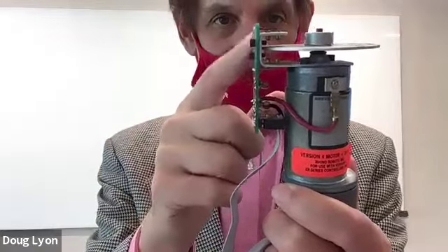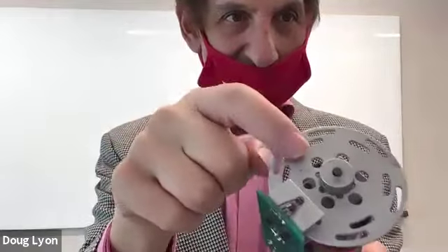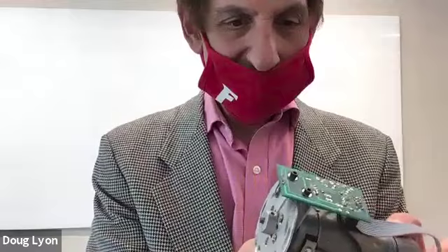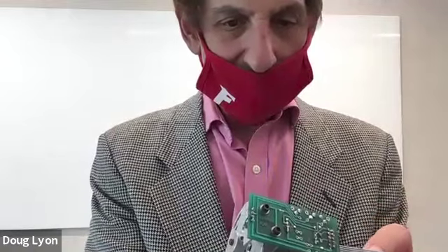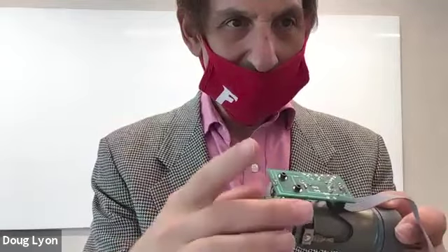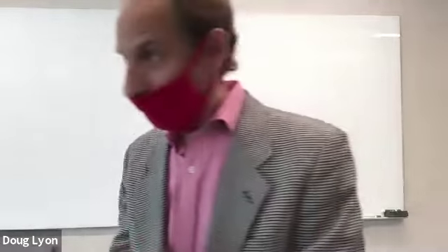You can see a couple of photo transistors, and you can see gray code has been carved into this metal disc attached to the shaft. So this has got no physical resistor at all. All it does is it measures the rotations of the disc, and that gives you the ability to servo this high gear ratio DC motor, which enables you to get high mechanical power into your servo joint. And I'll pass this around for people to look at so you can see.